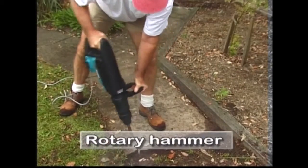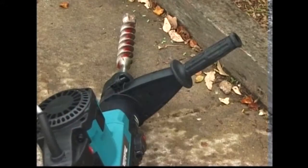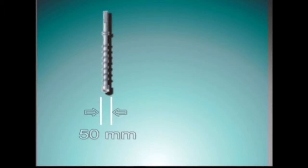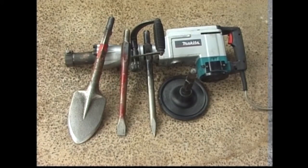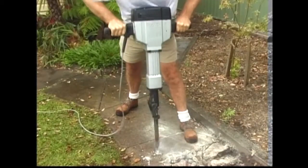Rotary hammers are similar to demolition hammers, but have an additional function. The rotary action permits drilling applications. When drilling, the handle is changed for safety and the rotary action engaged. Standard bits will drill up to 50 mm diameter. 160 mm can be achieved using a core bit. A range of bits for various applications is available for both rotary hammers and demolition hammers.